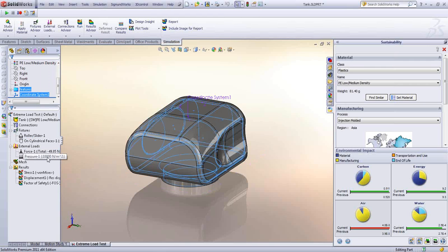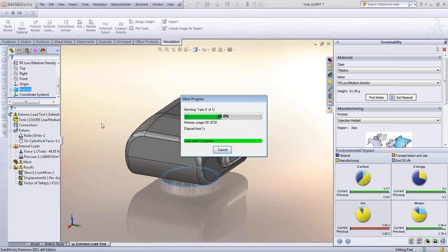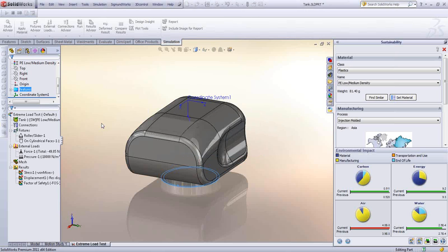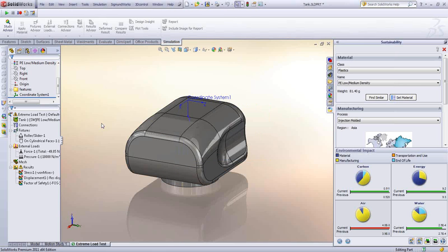A simple rho g h has led me to this number of 10,000 Newton per meter square, and I have fixed the part. I have a cylindrical constraint on the collar and a roller constraint on the face. So what I can do now is run SolidWorks Simulation and see how my design is holding up to the requirements. The requirements being the 5 kilograms book load and 10,000 Newton per meter square pressure inside.